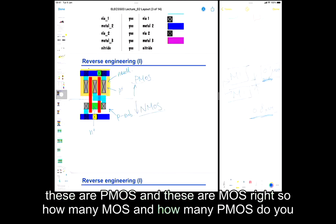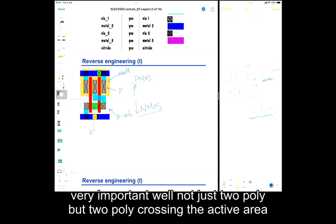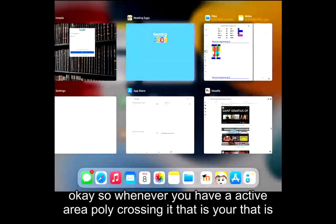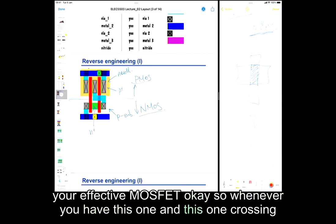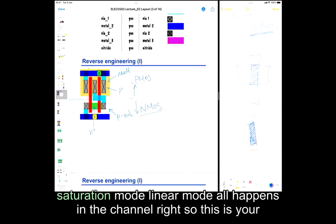So how many NMOS and how many PMOS do you have? Two each. That's right. How do you know? Yep, there are two polys. That is very important. Well, not just two poly, but two poly crossing the active area, okay? So whenever you have an active area with poly crossing it, that is your effective MOSFET. I'll draw it with another color. So whenever you have this one and this one crossing, your effective MOSFET is identified here, okay? All the main stuff happens, like saturation mode, linear mode, all happens in the channel, right? So this is your active MOSFET.